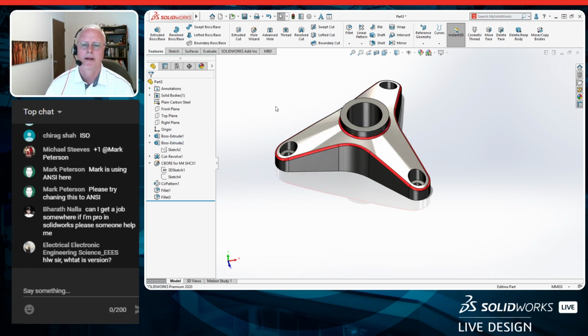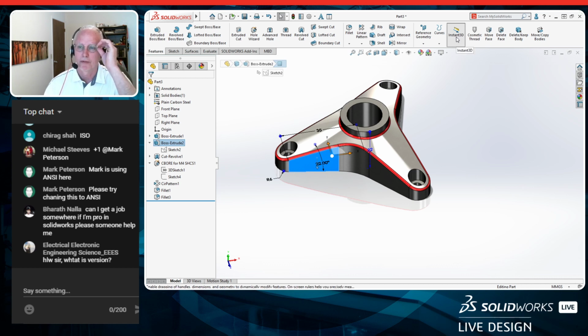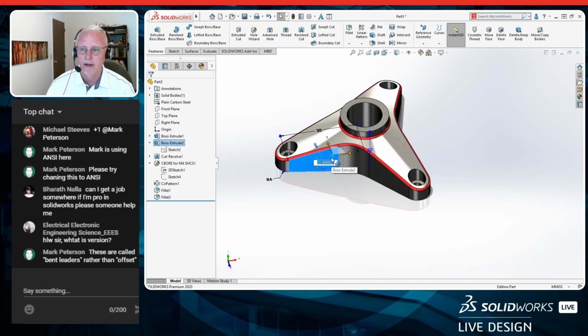One thing I want to point out here, I'm using Instant 3D. I personally prefer to use this. It allows me a single click on a dimension to quickly change that. You can choose to use it or not. I also use the Instant 2D, so I have very similar capability inside of the 2D environment.